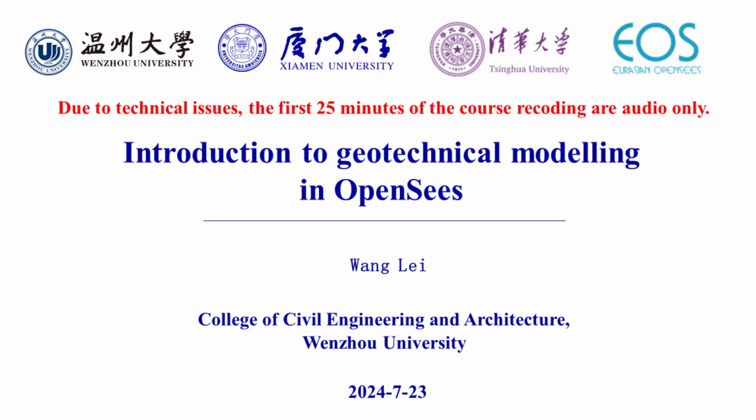So this is the whole model of the SSI system. After we build the whole model in OpenSees, we will apply the gravity load to the whole SSI system, and then apply the earthquake acceleration to the base of the soil to do the dynamic analysis. Then I will introduce how to build the model in OpenSees step by step.